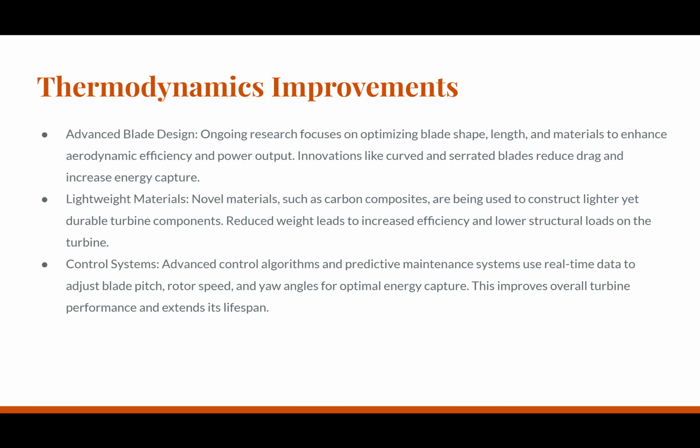Control systems. Advanced control algorithms and predictive maintenance systems use real-time data to adjust blade pitch, rotor speed, and yaw angles for optimal energy capture. This improves overall turbine performance and extends its lifespan.